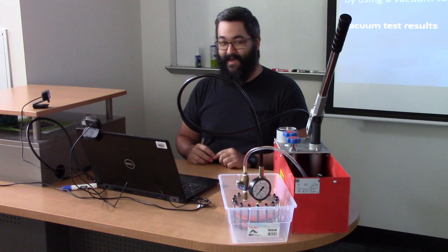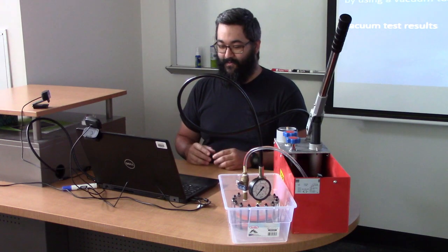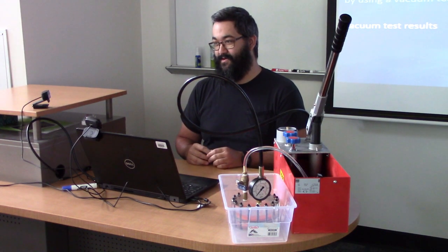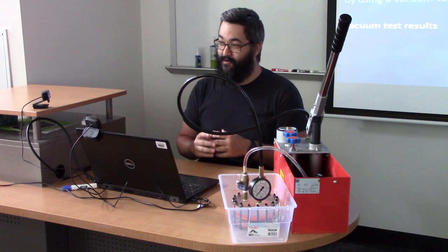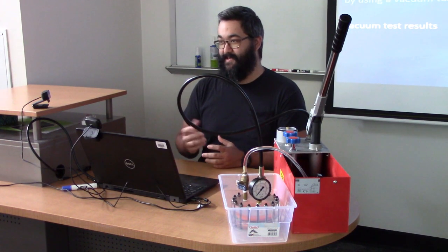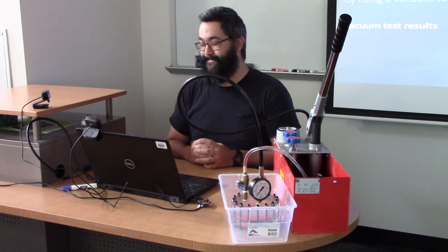So the inside or the outside of the 3D printed part, depending on where the dimensions are most accurate, we can apply an epoxy sealant to it that would encase the inside and would not allow the penetration of water through the part. So we can do post-processing like that to actually waterproof the prints. So that way it would seal it.